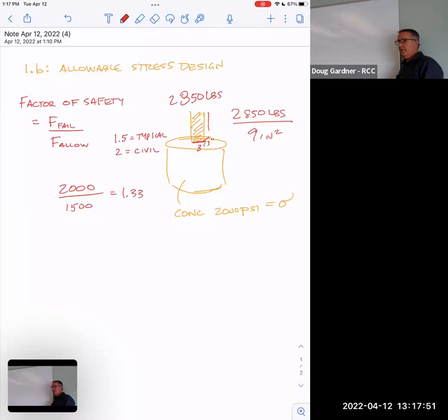It's 2 by 2 by 2 yards. 6 feet by 6 feet by 6 feet is 8 cubic yards. And so it's not much when you're pouring a bridge or something really large. But they actually have these little test cylinders. They're a foot tall and 6 inches in diameter, and they're made out of plastic. The truck pulls up and they fill 3 or 4 of those. I don't know how many, they fill a number of them, 3 or 4, and then they dump the rest of the concrete into the bridge.